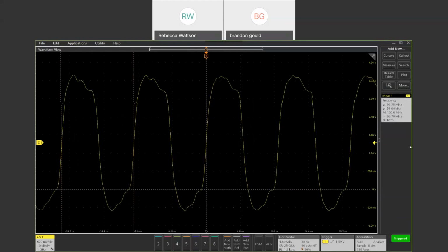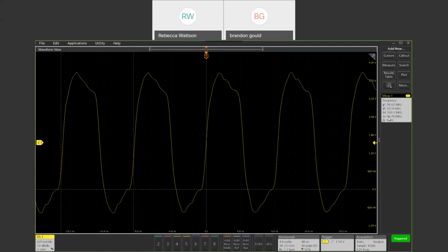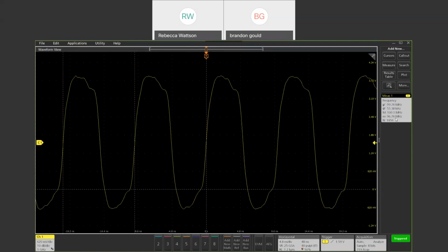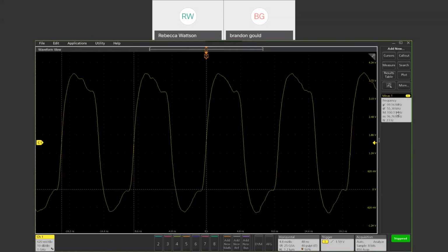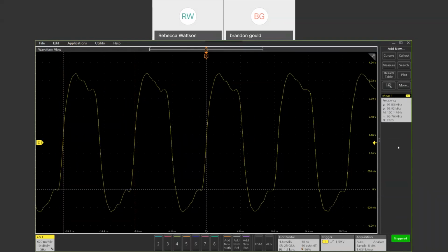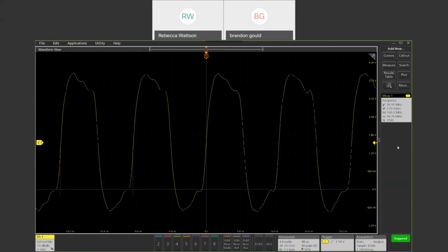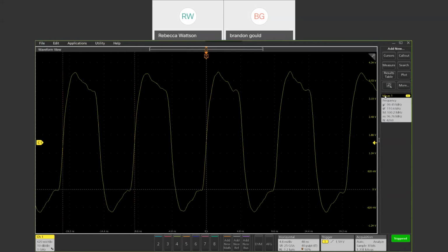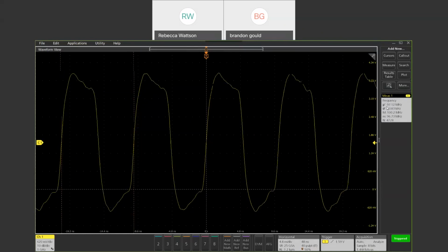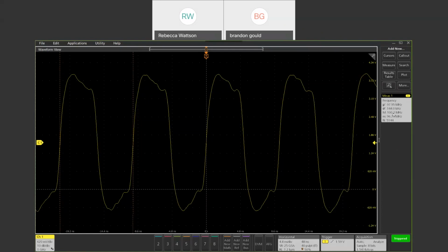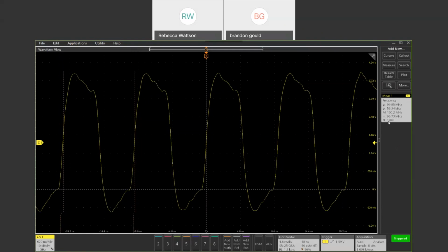So over here, I can now see that the smallest frequency that's been measured so far was 96.75 megahertz, and the largest was 100 megahertz. So we're going to turn on Spectrum View, which operates similar to an FFT. I'm going to show you the differences in this demo. And we're going to set our view of the spectrum to incorporate the highest magnitudes we've seen and the lowest frequencies that we've seen.